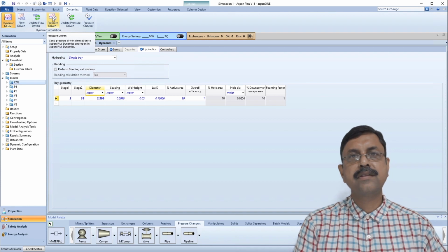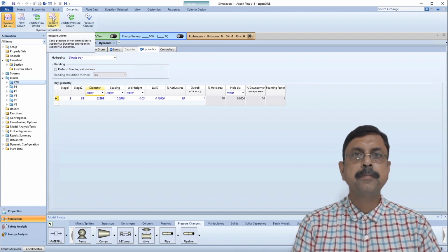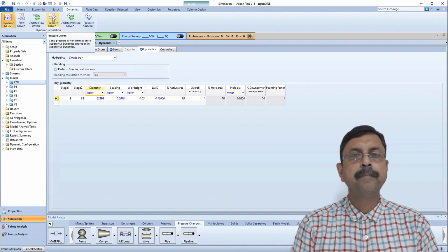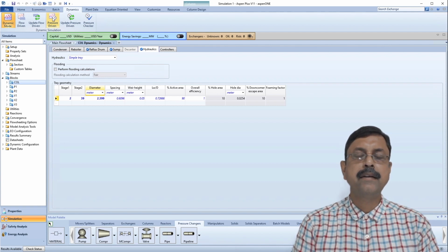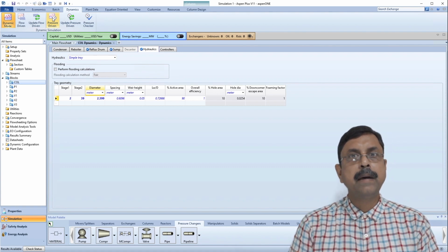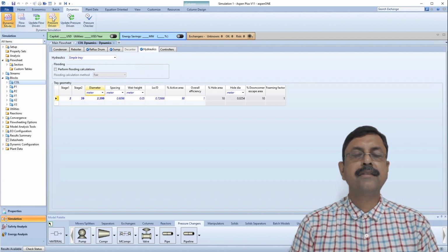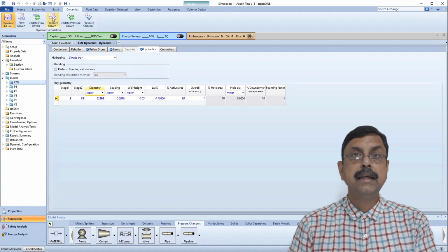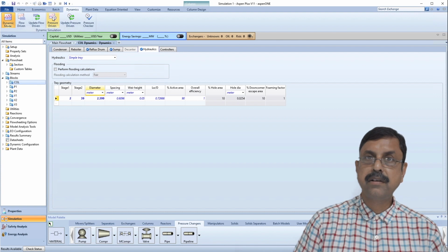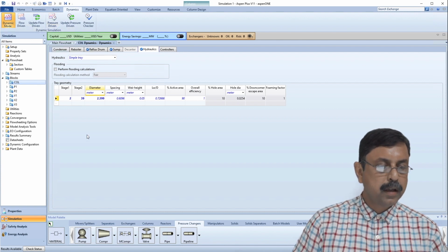The flow first comes at 5 bar pressure and then it depressurized at 1.262 bar, and then in the column it operates at 1 bar and then it goes out, and through the pump it increases by 6 bar, and then it is depressurized by the control valve by 3 bar. So we shall use the pressure driven simulation. So we have to press pressure driven simulation.